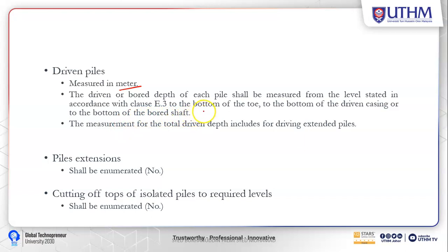Maybe we have the precast pile, or sometimes we are doing the in situ pile technique. If you are doing the pile in situ, sometimes you need to do the boring using a boring machine, an auger machine. So you need to do the piling construction step by step, according to the specification of work.